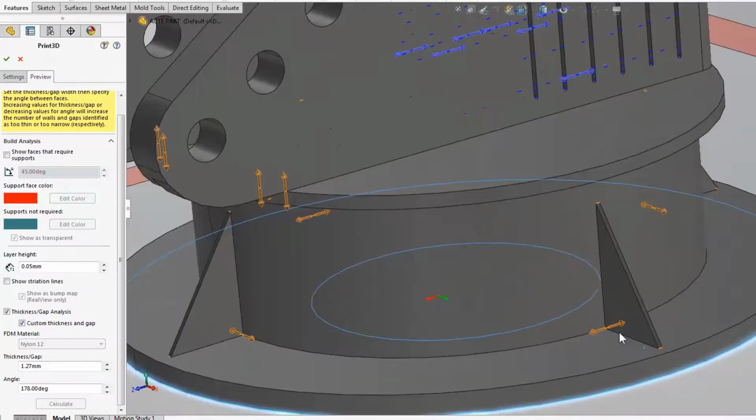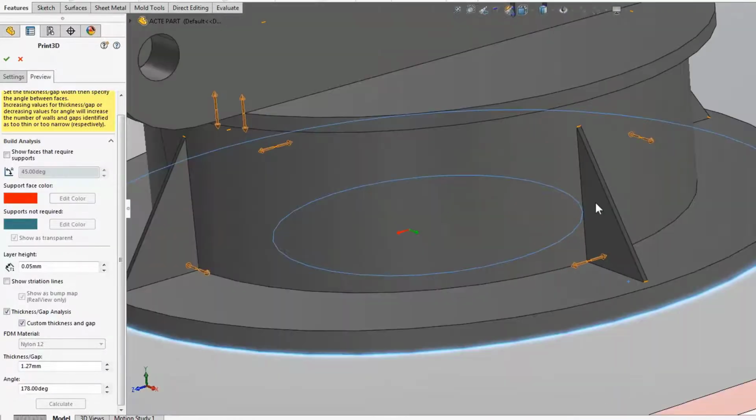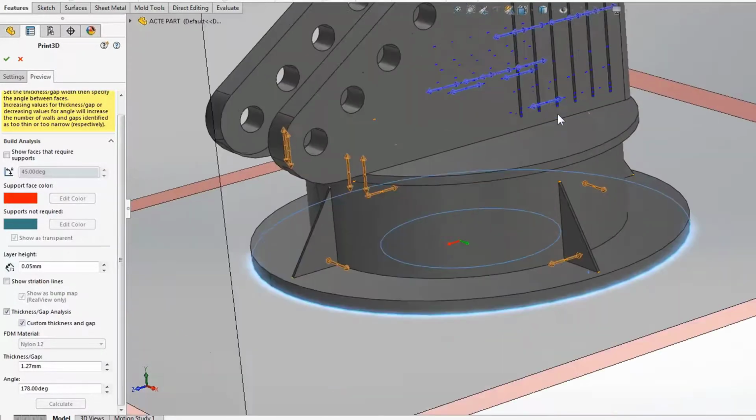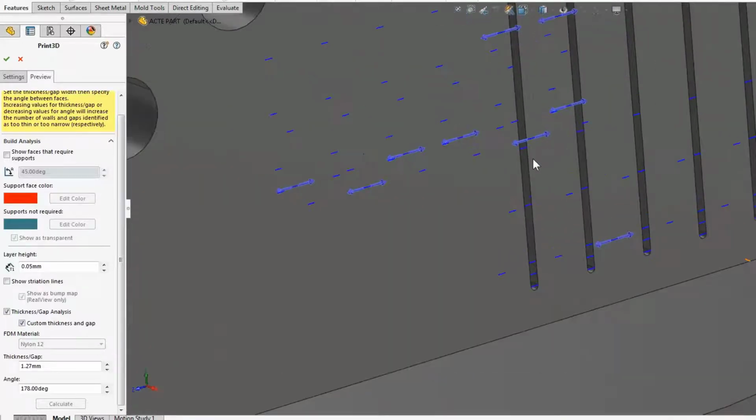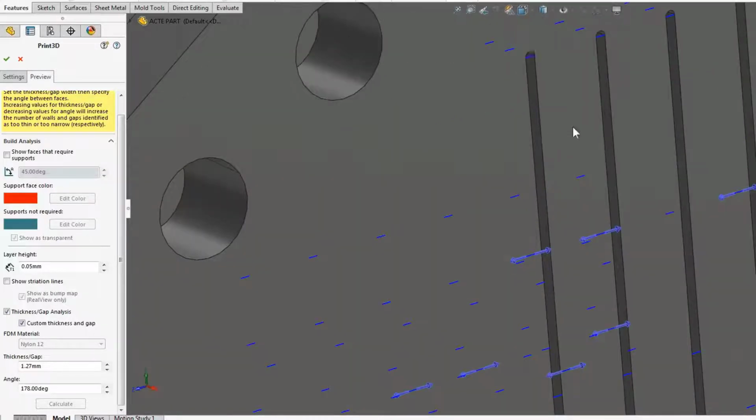I'll show that in the actual 3D printing software that we use to show that better. You could also get surface quality issues with thin walls, and then small, thin gaps run the risk of either closing up if they're too close together. They'll just fuse right together and you won't have your gap, or the support that will be needed for the top would result in what is known as rat nests or bird nests, where the material just sags.